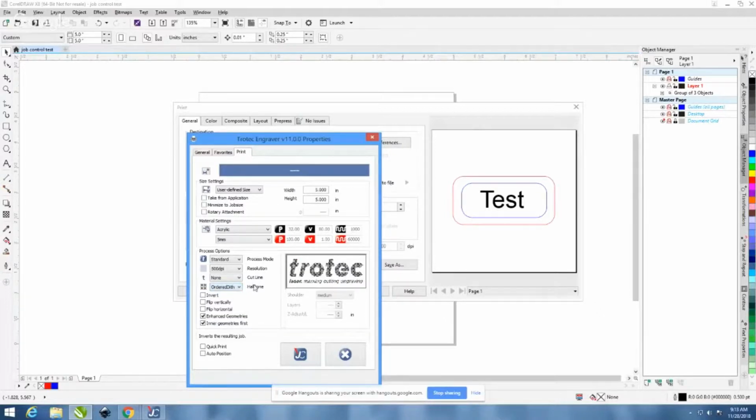Yeah, so when you take a color photograph to send it to the laser, obviously the laser can't engrave in color. So it does a process called dithering. It's taking a series of a dot pattern to approximate the colors in your drawing. And these are the different methods that it uses to do it. The ordered dithering is basically a fixed pattern throughout. Some people really like it. They think it looks great. I find that pattern to be kind of distracting, so I personally don't like it. That's why I prefer Stucki like Anthony does. But some people really prefer their dithering. So like Anthony said, beauty is really in the eye of the beholder.